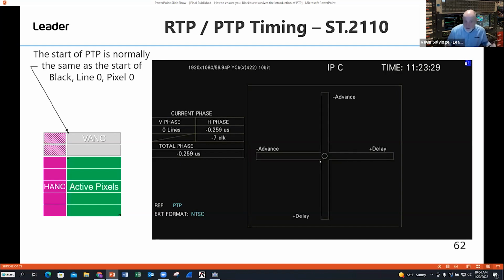Like you do with the video traffic, when we talk about 2110 and the timing and all of that, you've got to put the same thought into your PTP network. And you don't want, as Steve just showed you there, to build bottlenecks where the messages are going quicker out than they're coming back, because it's a recipe for disaster.